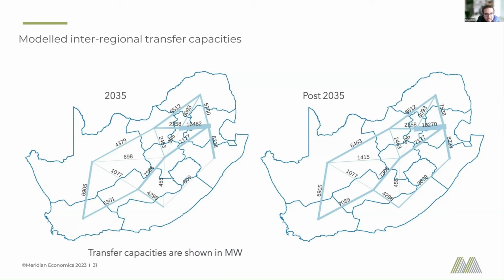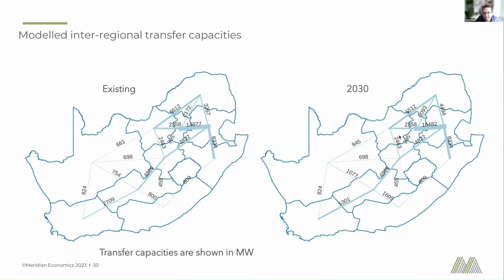In terms of how this is actually represented within PyPSA, we've used a derating model. We take the line capacity at its absolute maximum, so if it was 2035 or 2040, we make our base network have that maximum capacity, and then we derate that line. So as far as PyPSA is concerned, it would be a 7.3 gig connection between these two regions, but then that's derated down to 4.8 gigs in earlier years.